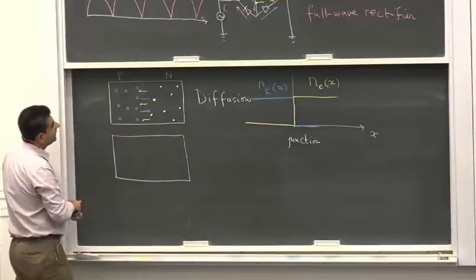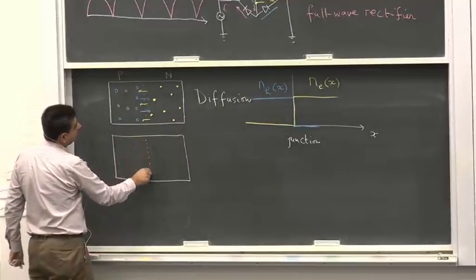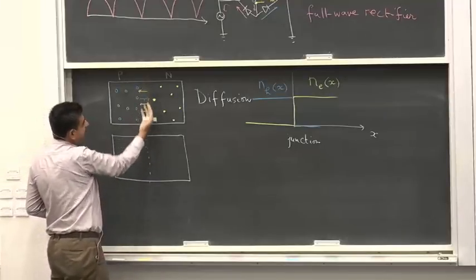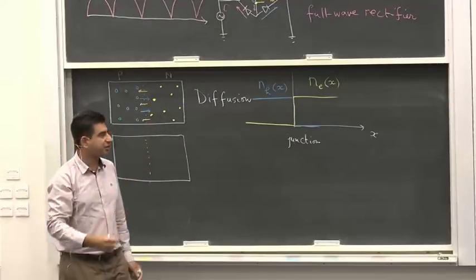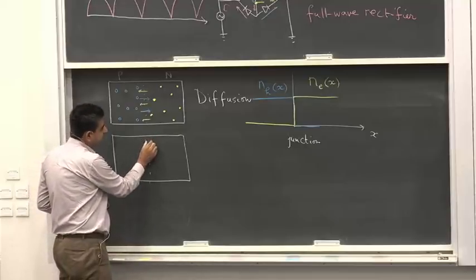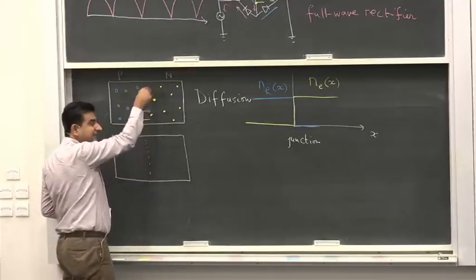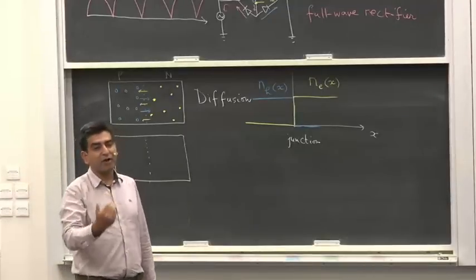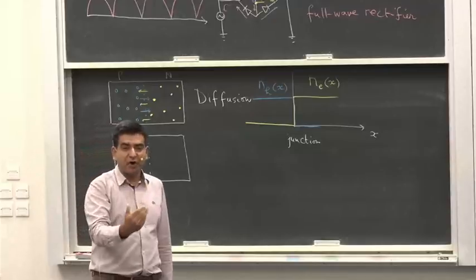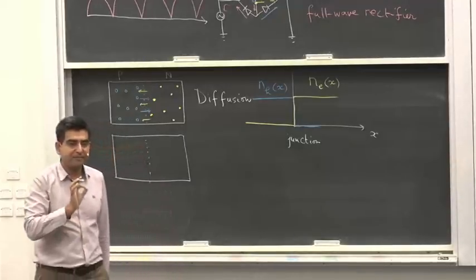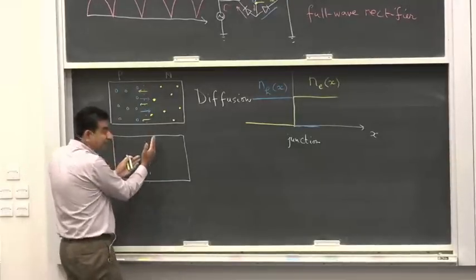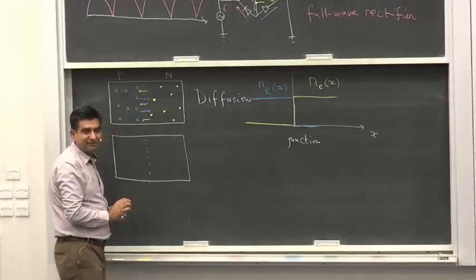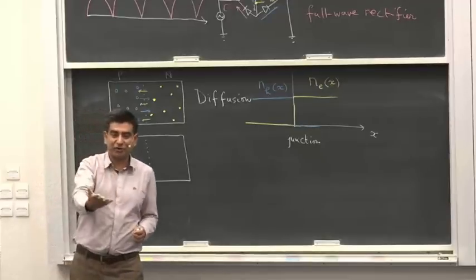However, now diffusion is allowed, and across this junction some of the electrons inside the n-type material move across the junction, and the region in the immediate vicinity of the junction inside the n-type material becomes devoid of electrons. Devoid means khali. This region in the immediate vicinity now doesn't have electrons. Now it's given off its electrons.